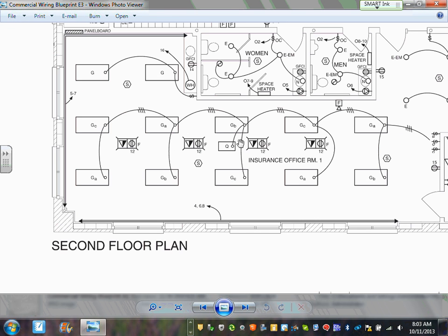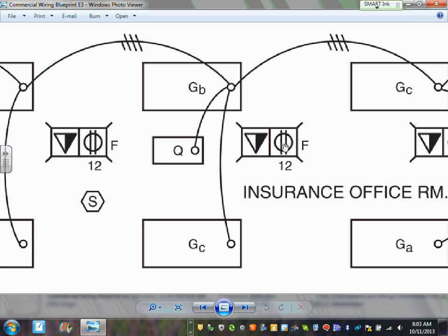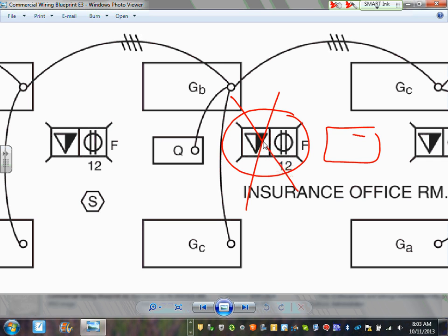Okay, so you can see what they did here. These are phone data floor boxes. They have a box in the floor with a conduit. The box comes designed in 2 sections. In one section they put the low voltage. In the other section they put the high voltage. I want to bring to your attention, guys, this is the exact one we're using in our project. We're going to have a box, literally a box exactly here, where you're going to have a receptacle on one side and a low voltage on the other side. So here's another example of how you do it right into the floor.